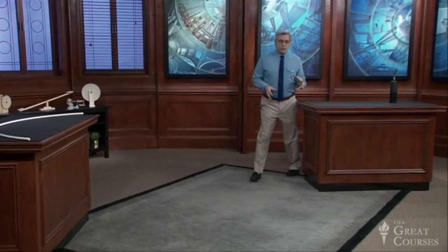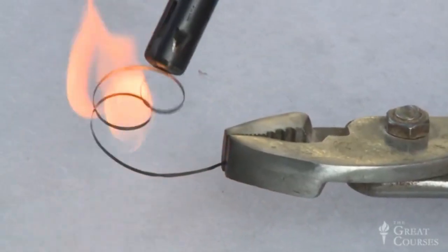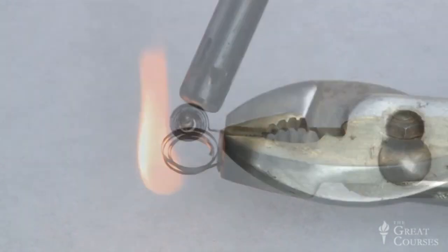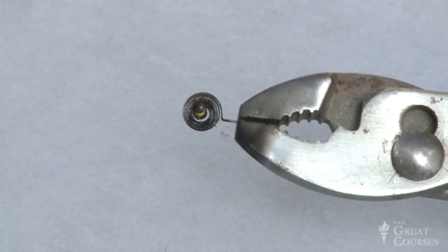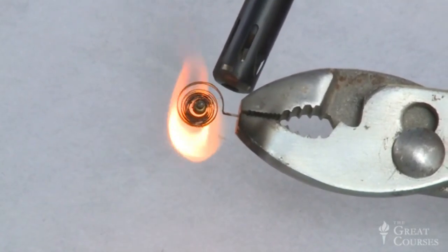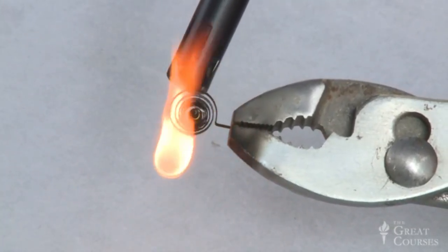Now, in a bimetallic strip, the amount of bending for a given temperature change depends on both the length and thickness of the strip. A longer, thinner strip bends more than a shorter, thicker one. And that's why most thermostats use a very long, thin bimetallic strip that's been formed into a coil so it can fit within the thermostat housing. Watch how much thermally induced bending this coil experiences with just a modest input of heat.